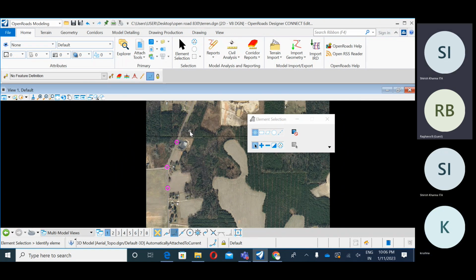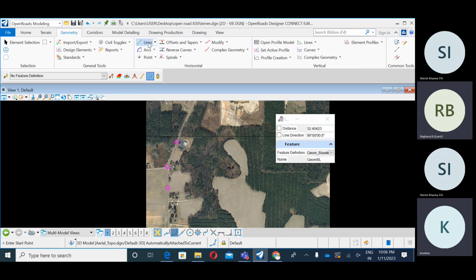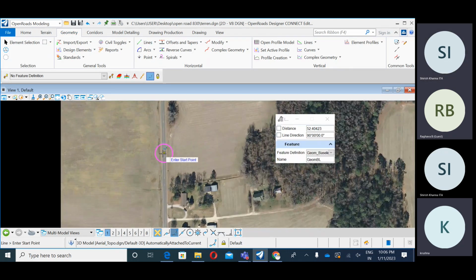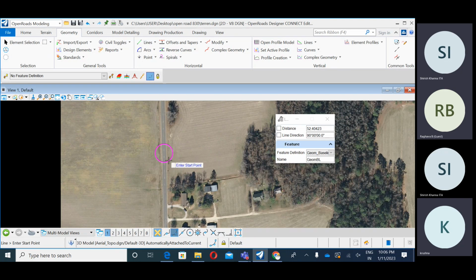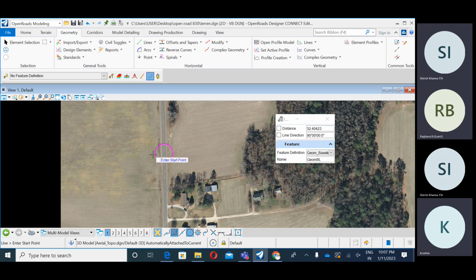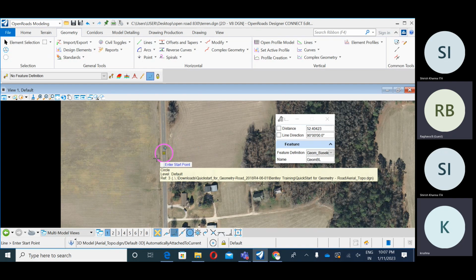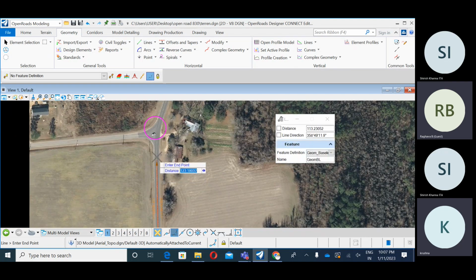It's very easy. We have to go to Geometry, take the line, and start it with its center, so directly we get a center. If you don't get a center directly, we need to turn on the snapping. Here in the bottom we have center snap. It means if you click anywhere on the circle, you get the center only, by default. Now I need to click on it. We click with this arrow on the circle center, and directly we get the circle center.